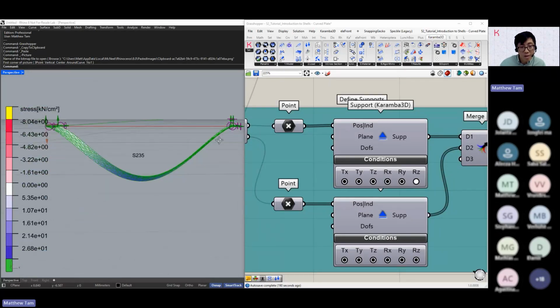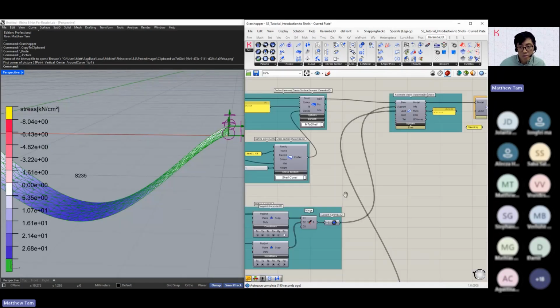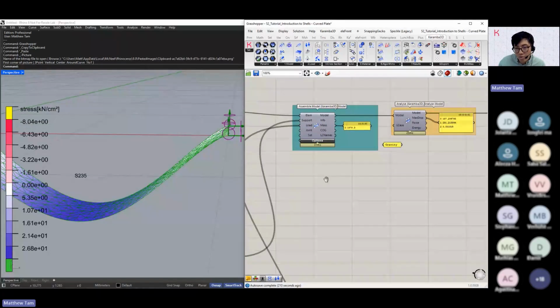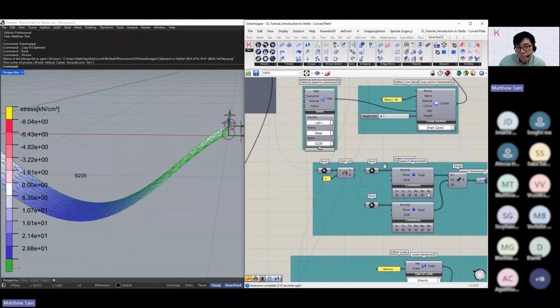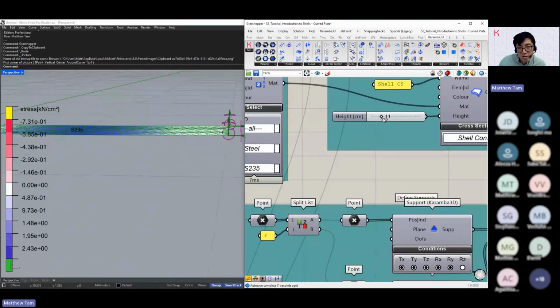also there, you can see the deformation shape, of course, would adapt according to our support condition. And now we no longer, of course, because we fixed it now in the Z direction there, have any more rigid body modes issue in our problem, or in our model analysis. We can, of course, set the height. And in this case, I'm looking at the principal stresses.